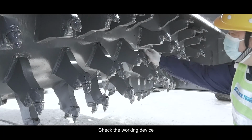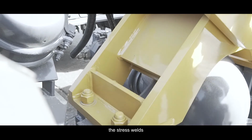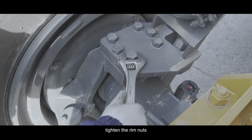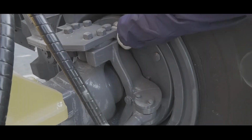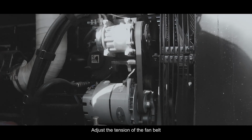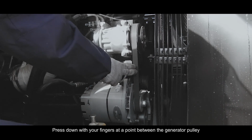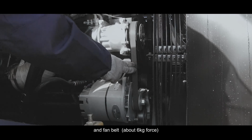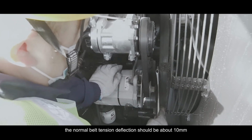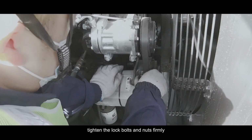Check the working device, the front and rear frame, the front and rear axles, the stress welds, and the fixing bolts for cracks and looseness. Tighten the rim nuts. Check the brake clearance and the wear condition of the brake pads. Adjust the tension of the fan belt: press down with your fingers at a point between the generator pulley and fan belt, with about 6 kg force. The normal belt tension deflection should be about 10 mm. After adjustment, tighten the lock bolts and nuts firmly.